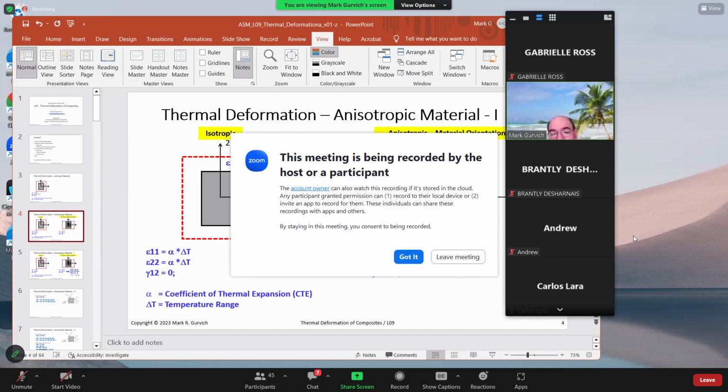So what we see from this example, if we consider deformation in the material coordinate system, so 2 and 1 correlate with material orientation, I see with my cursor, we had a rectangular piece of material, we heated it, it expanded, but the shape also will be rectangular after deformation. The only difference would be that strains in both orientations will be different.